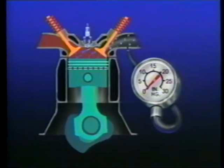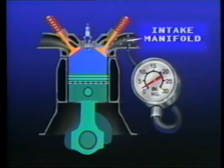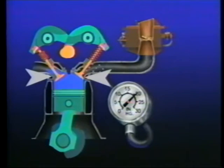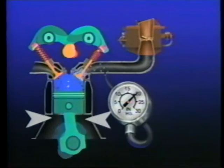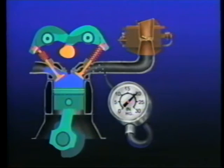A vacuum gauge is still a very important tool for diagnosing engine problems. Before we answer this comparative statement, let's review how engine vacuum is produced. As each piston moves downward on its intake stroke with the throttle closed at idle, vacuum is created in the intake manifold. In a cylinder which has low compression due to a leak in the cylinder seal, such as a valve or ring, when the piston moves downward on its intake stroke, air would also enter through the cylinder seal leak.